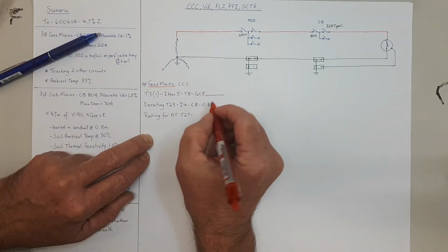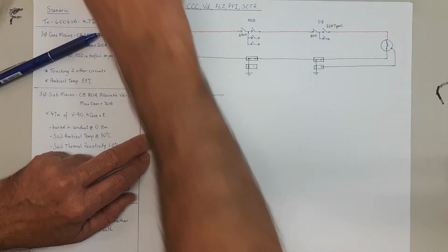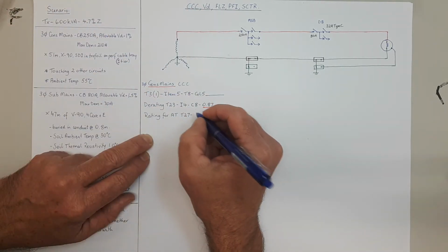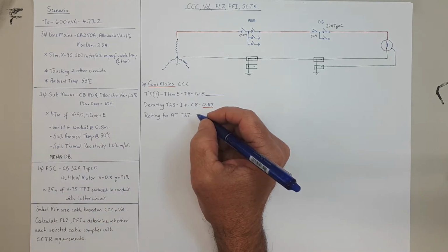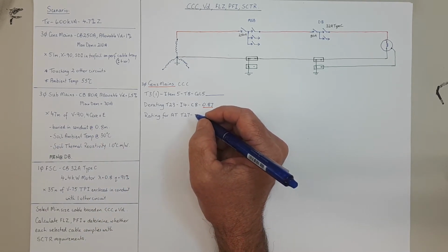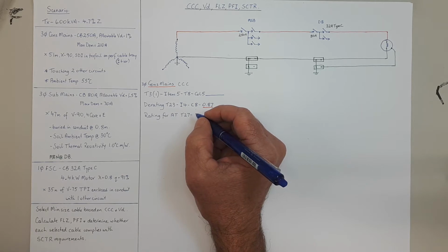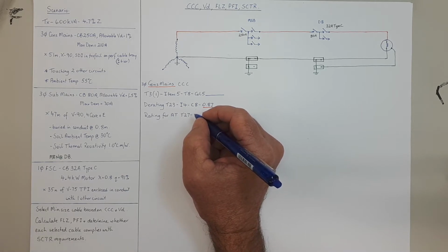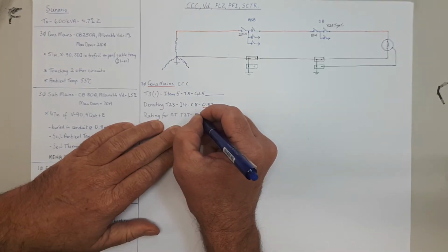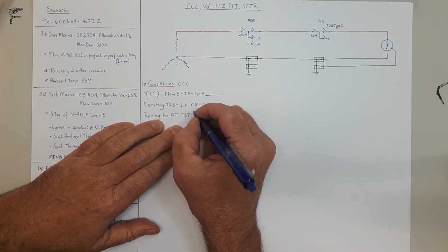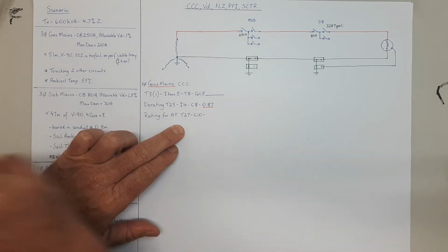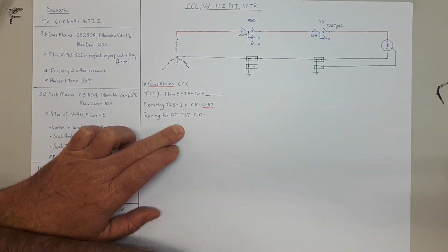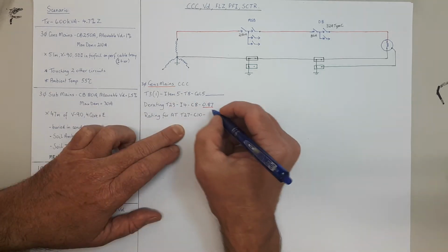And for ambient temperature is always table 27. And so what we've got to find in table 27 is we're looking for the temperature. And you'll see 55 degrees is in column 10. Run your finger down to 90 degree cable and it's 0.81.